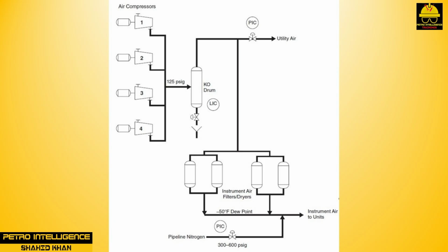The air compressors are set up to produce approximately 125 psig air pressure into the system. Because the instrument air (IA) system is the more critical system, pressure is controlled to 100 to 105 psig. Utility air (UA) has no pressure control.